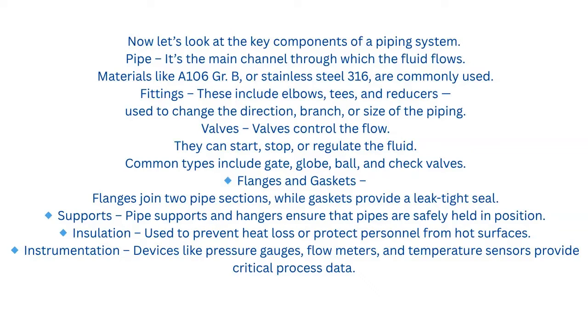Valves. Valves control the flow. They can start, stop, or regulate the fluid. Common types include gate, globe, ball, and check valves. Flanges and gaskets. Flanges join two pipe sections, while gaskets provide a leak-tight seal.